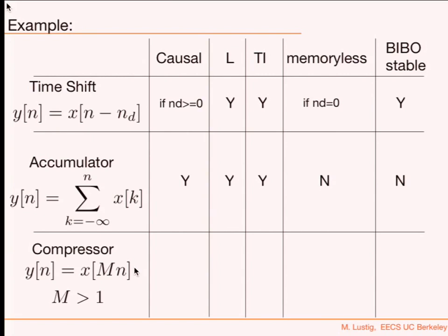Linear? Yes, it is linear, actually. Time invariant? No, it's not time invariant. Memoryless? No, because you have to save samples. And what about stable? Yes, right, because it's only the same samples at the input. Okay, great.